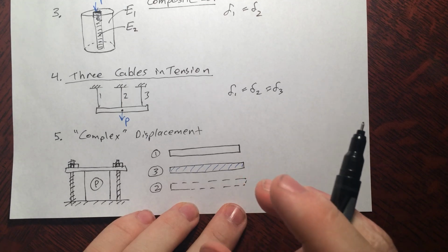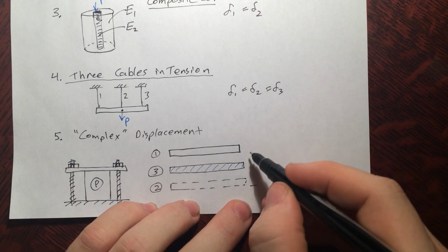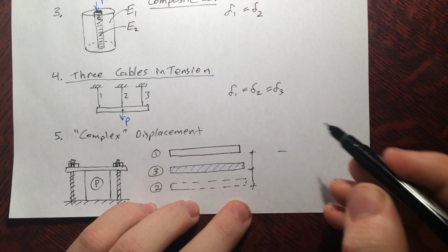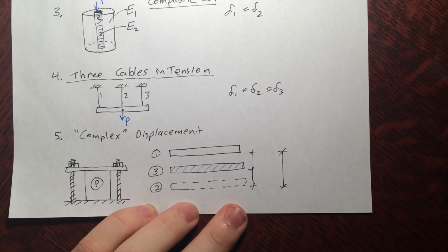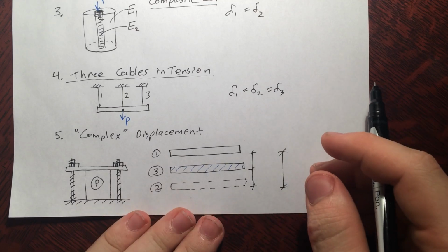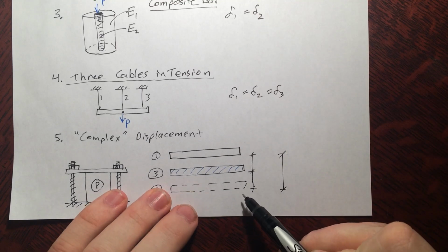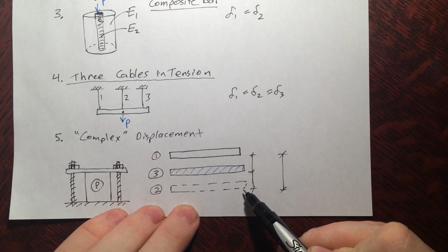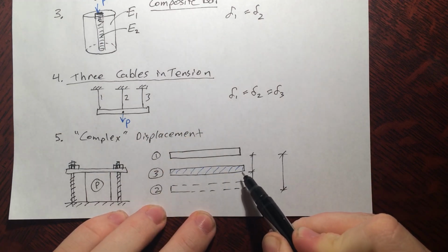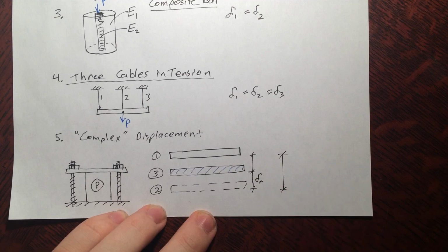So the final displacement of the plastic and the final displacement of the bolts are basically these distances here. I'll measure relative to the bottom of this plate. You can pick any point on that plate, but it's essentially the same. If we measured it all from the top, it would be the same. I measure from the bottom for no particular reason. So that's the amount that the plate moves down and then back up. You can imagine this is the point where those threaded rods start to be under some sort of tension. They start to displace. So the displacement of the rods is this bit here.